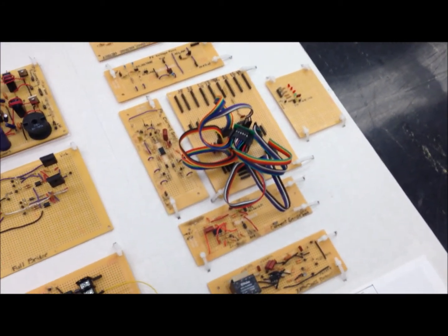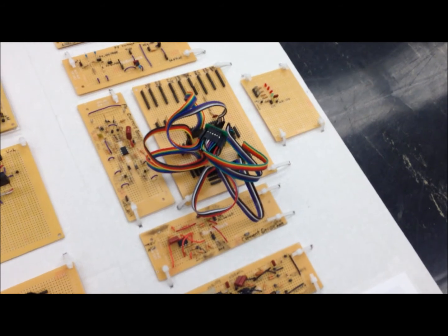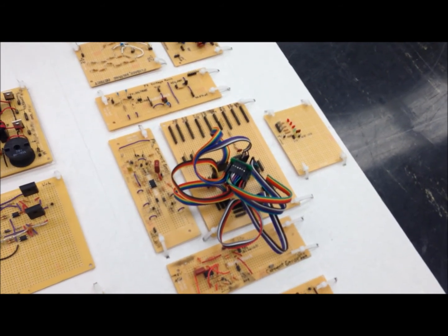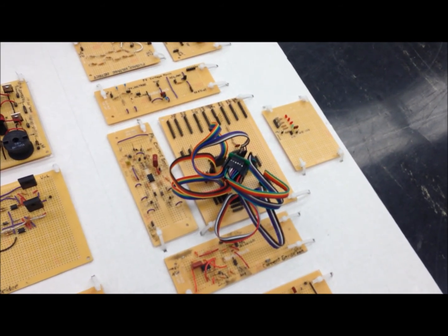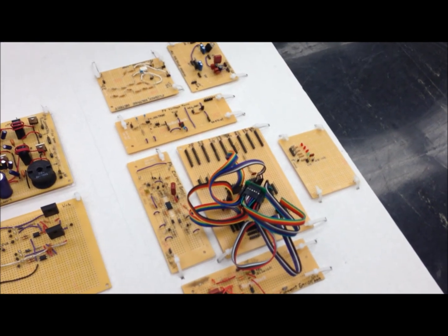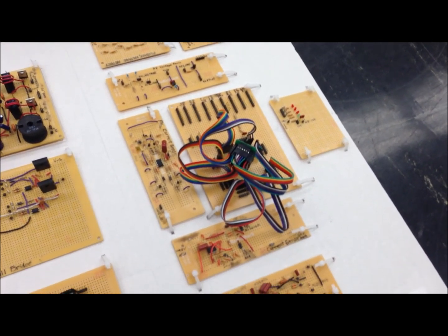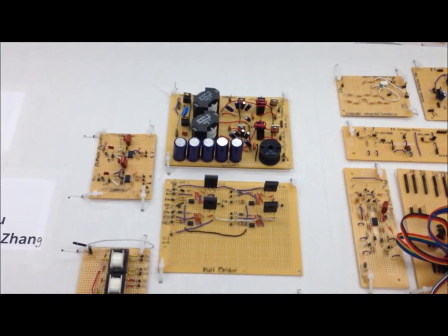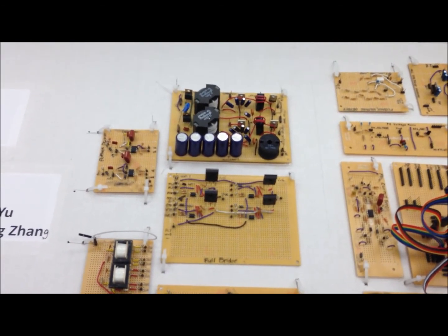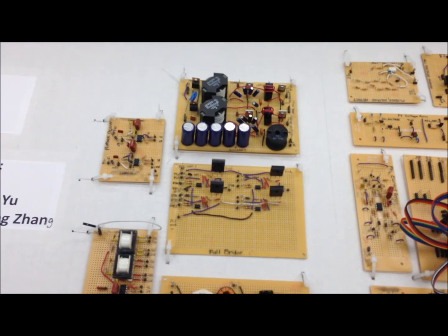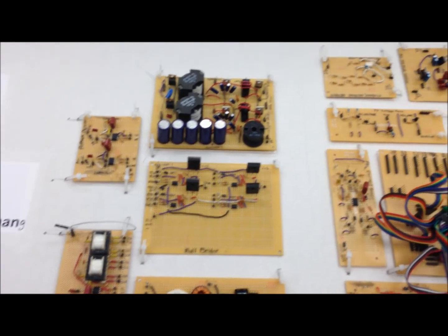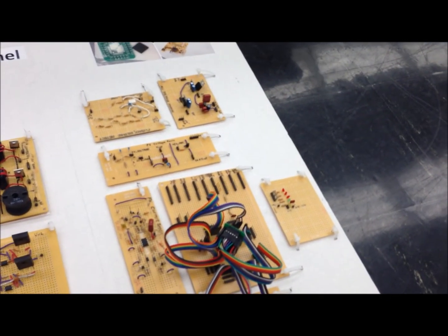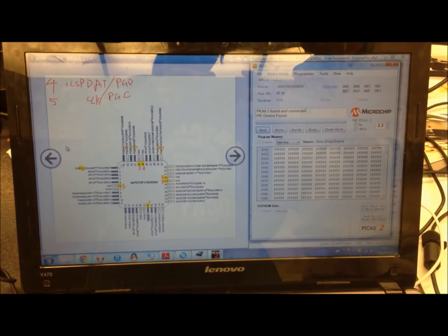The microprocessor uses a zero detecting and phase-locked loop to generate time-shifting duty cycle PWM signals to drive MOSFET switches, thus controlling the flyback converters and the full bridge to make the output synchronize with the grid. Sensors and protection circuits are made to ensure each stage is working properly.